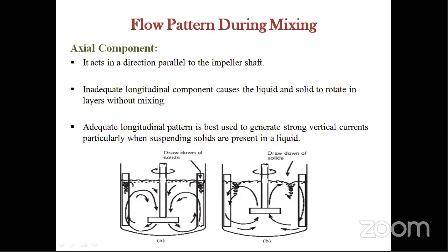A few solid particles are settled or suspended at the bottom of the tank. When they settle at the bottom of the tank, they are not mixed uniformly, or not mixed well with the liquids. This happens when your speed is slowed down. In case of solid-liquid mixing, you have to maintain an optimized speed. It should not be too high a speed or too low a speed.